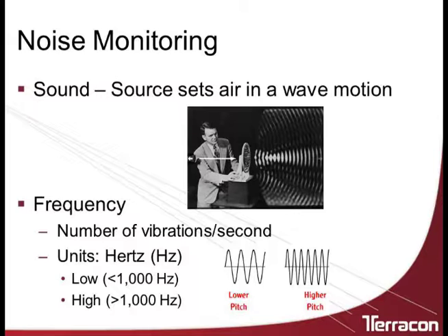Okay, and there's a point. When you talk about the various frequencies, you have everything from 63 all the way up to, I think, about 16,000 frequency. Anything below 1,000 is indicative of a low frequency. These type of waves are very long. They're very difficult to control. If you've got equipment that has a low frequency, you have to almost totally enclose it because it will find ways around things, through things, very difficult to control.